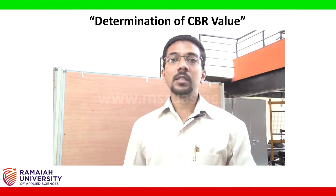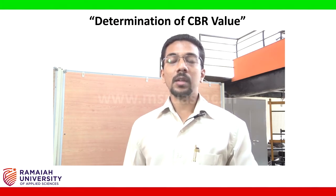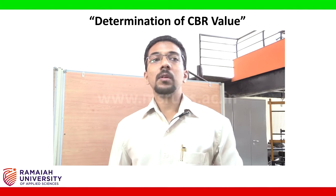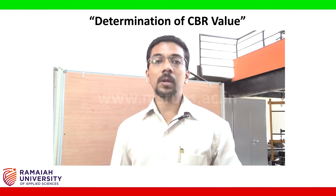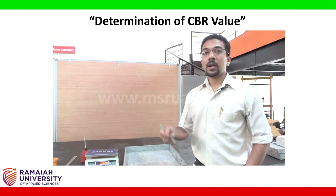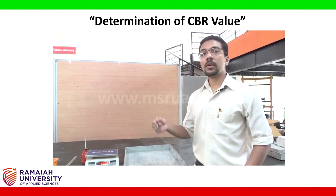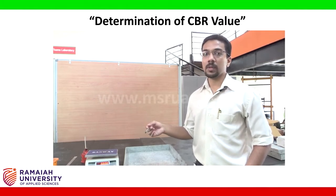This particular experiment was developed by the California State Highway Department, and it was later adopted by the Bureau of Indian Standards for the determination of strength of the subgrade material or pavement material. This experiment is as per IS 2720 part 16, and according to this specification we need to understand the various experimental setups that we need to use to conduct this experiment.